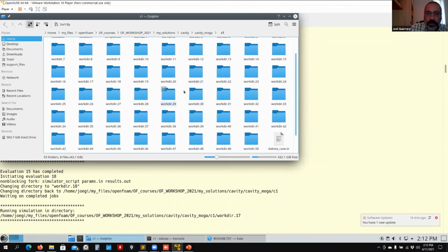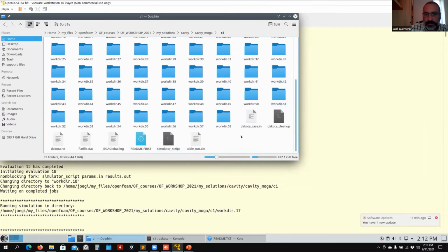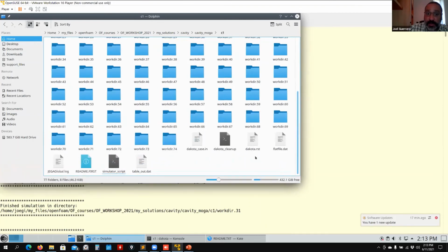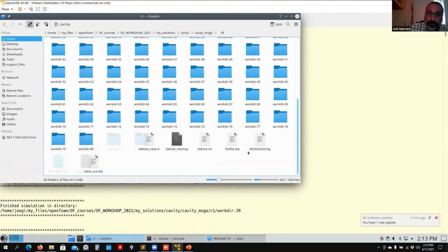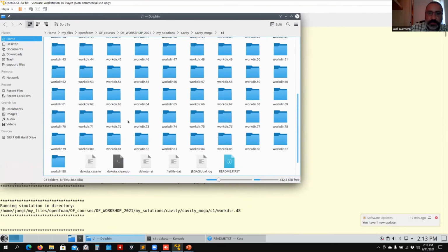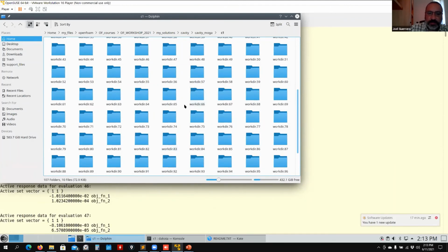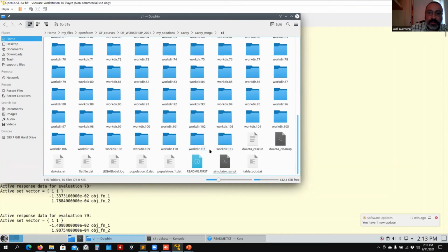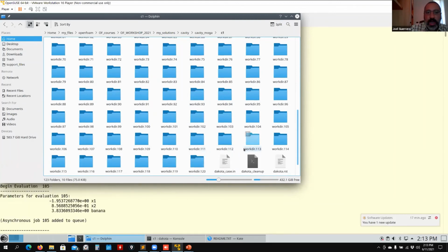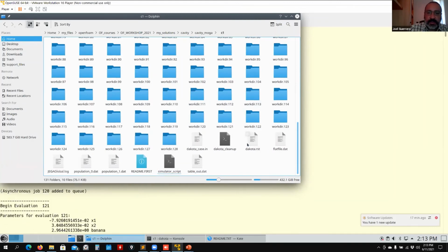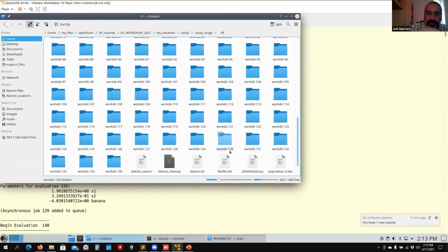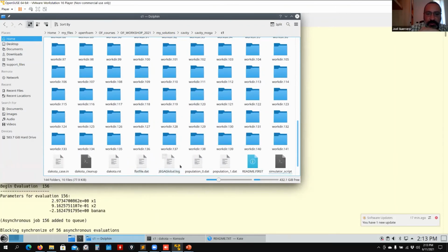Okay, so this is the problem with multi-objective optimization. Now that you need to use these derivative-free methods, they often compute a lot of function evaluations. Okay, so again, you can control also the maximum number of evaluations, everything. But at the end of the day, it will generate a file where you have the Pareto. Okay, so see that also it is saving the populations, everything.